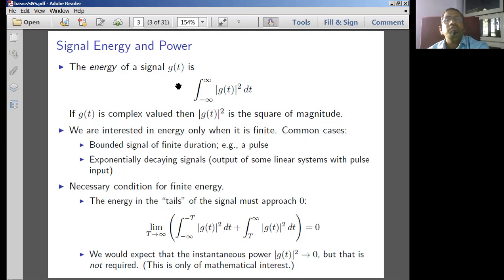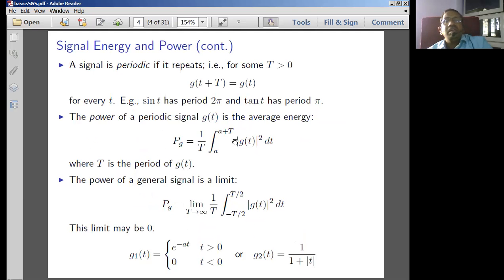Now similarly, if we find the average value of this particular energy signal, we are going to get the power signal. So this is the energy signal: integration of g of t whole square dt is the energy. And if you find the average value, what is T? T is the time period of the signal under consideration. So if you find 1 by T, means what? You are finding the mean value of this entire signal in terms of energy. If you find the mean value of that, we are going to find the power which is there inside this particular signal. So therefore the power signal can be represented something like this for us. Okay.